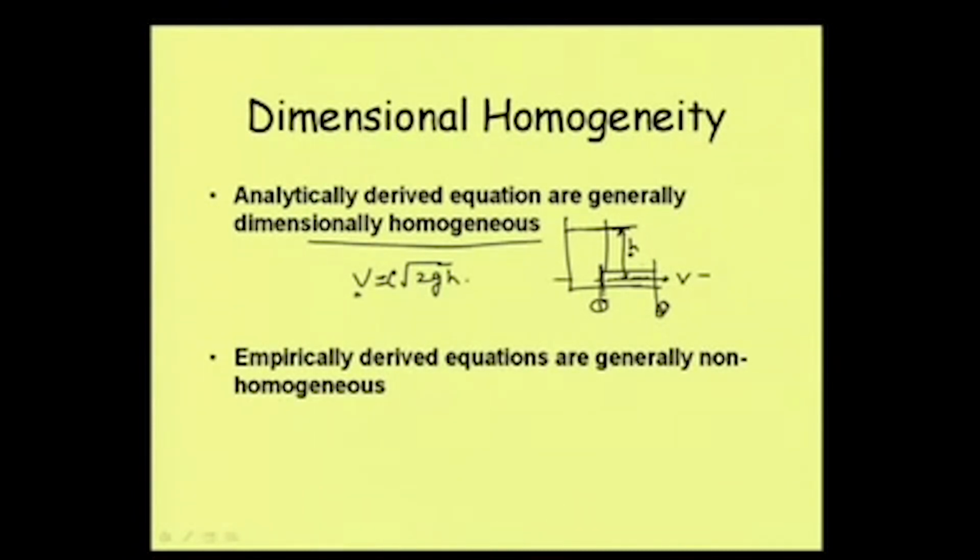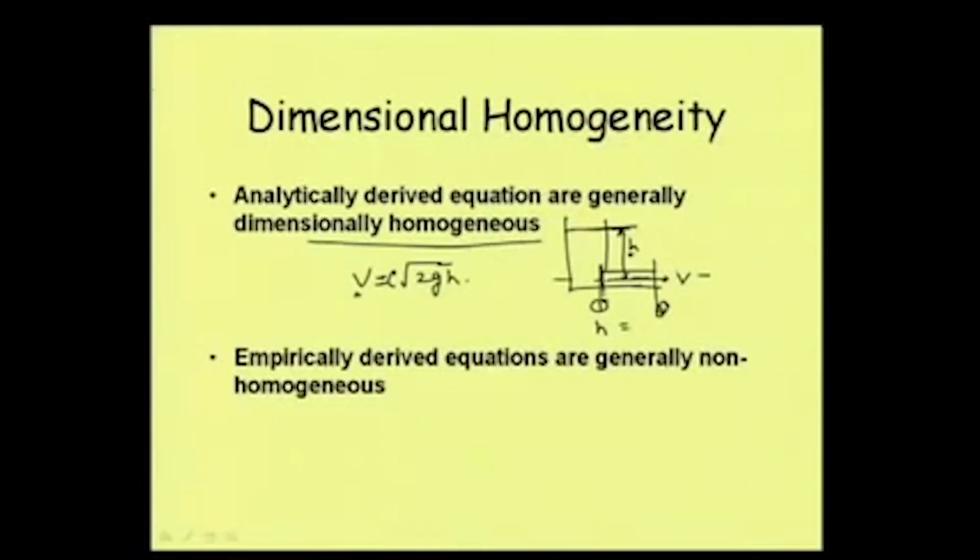So from this you can write, here is h, and this is equal to the head here. Here the pressure head is 0. Zero means we are not talking about absolute pressure, we are talking about atmospheric pressure. When we say pressure head is 0, we mean that the pressure is atmospheric. As it is open to the atmosphere, the pressure will become 0. So what remains is only velocity. So the head will be v squared by twice g, and z here is of course 0. From that we can write that v is equal to root over twice g h.